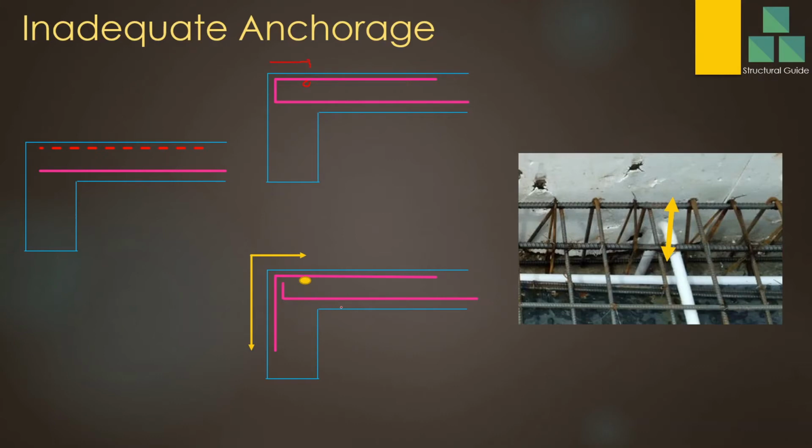But in this case, the top reinforcement bar does not continue like in the above figure. So you anchor into this beam. We have to provide the anchorage length from the restraint bar. This is the restraint bar. This is the beam reinforcement. From that, you have to provide this anchorage length. This is called the tension anchorage length, because this bar is provided to take the tensile stress, because we have a hogging moment there. So therefore you have to provide the tension anchorage length there.